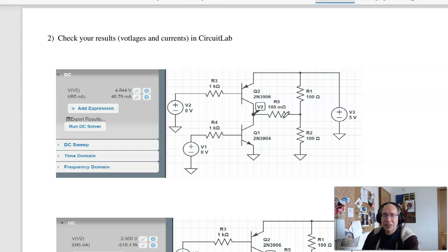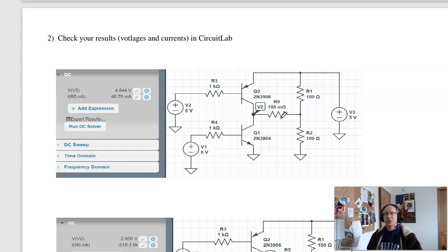That just lets me measure the current. It's something close to 0, but not quite. You can actually buy 0.1 ohm resistors. This is the reason that they sell them. If I want to measure current, I'll just stick a 0.1 ohm resistor in series and then measure the voltage drop. Voltage is easy to measure, current is hard, so that lets me basically measure current.